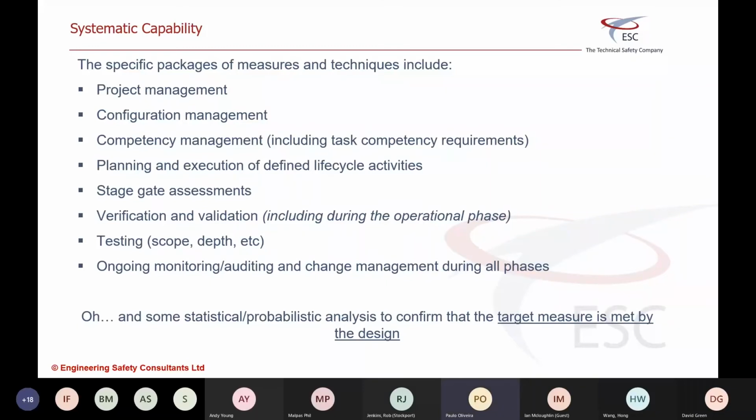Stage gate assessments, your functional safety assessments. Verification and validation, including during the operational phase, validating that what you have is doing what it should be doing and it's meeting your estimates. Testing. What's the scope of your test, the depth of your test, the boundaries, etc. Ongoing monitoring and auditing, and change management during all phases. Change management is not only after operations and maintenance.